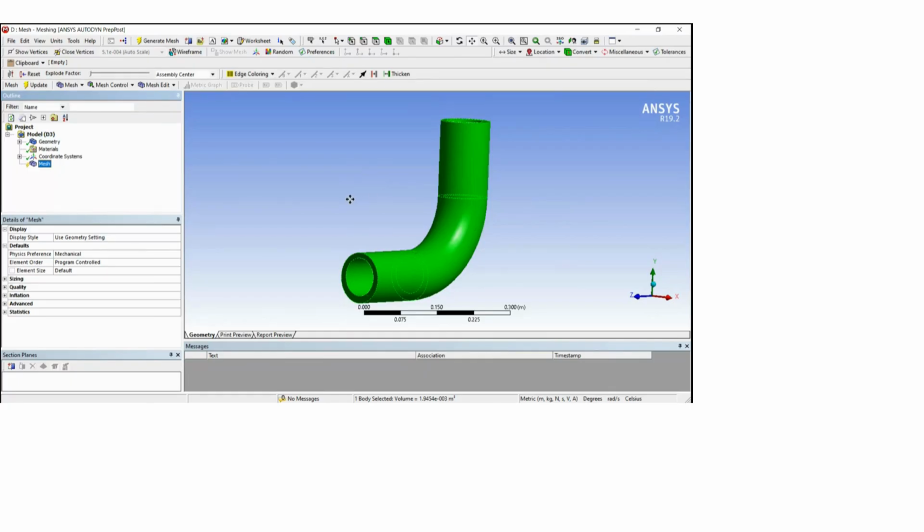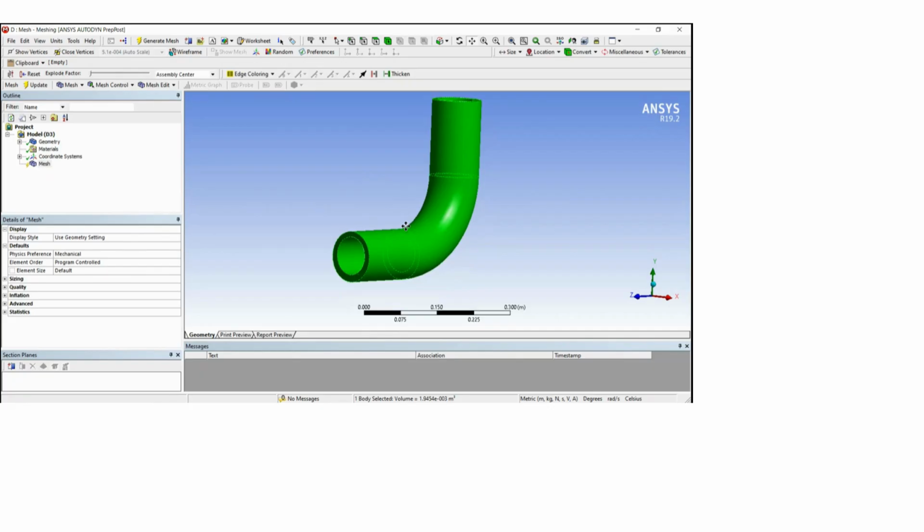Okay, so this is one of the criteria to check the separable bodies. Okay, so what basically is step meshing? Step meshing is the meshing in which we can make a hexahedral cell and we can make a structured mesh. Okay, hexahedral cell and the structured mesh.